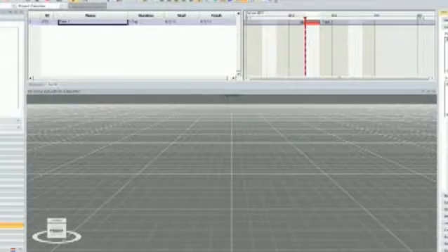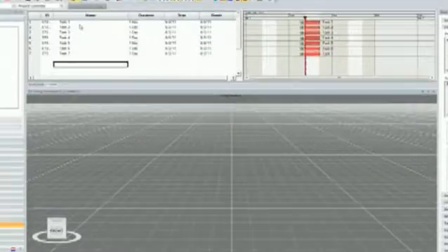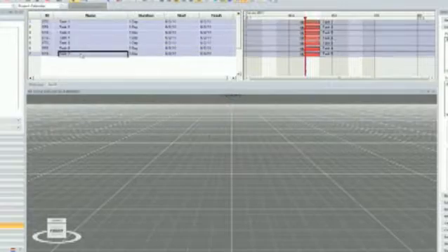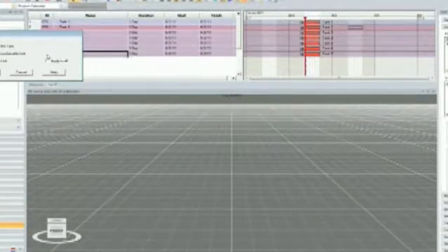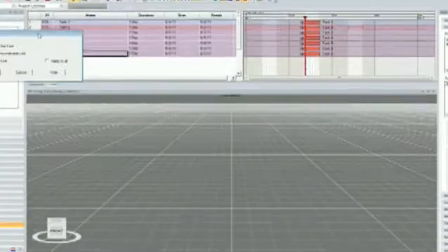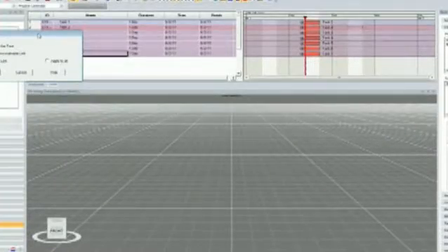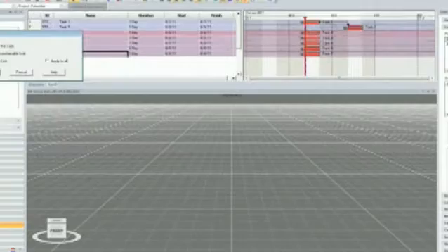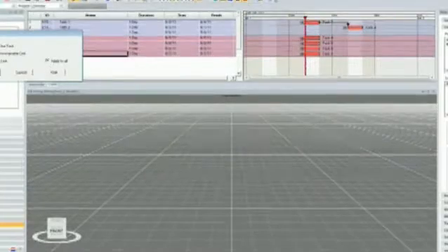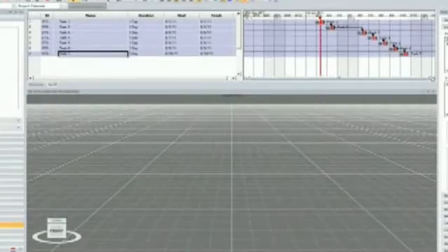Now if I highlight my links task here and I come back to my schedule and I can just create multiple tasks, I'll highlight 1, I'll hold shift, highlight 7, I'll link these tasks in a chain, and I have automatic rescheduling on. If I had it turned off, I'd push F9 like in Primavera and say, okay, reschedule that. Oops, I'm going to apply to all, sorry, take that box. And now you'll notice I've just created the logic in Synchro.